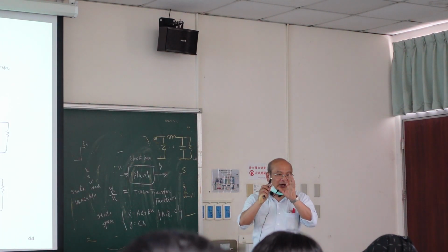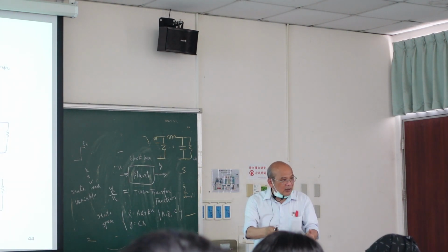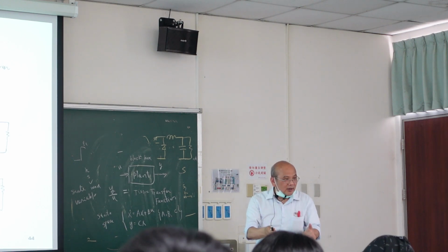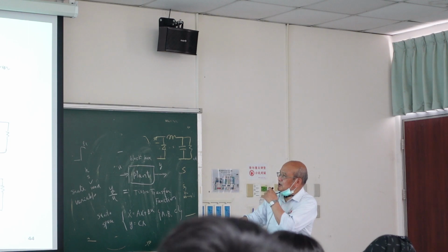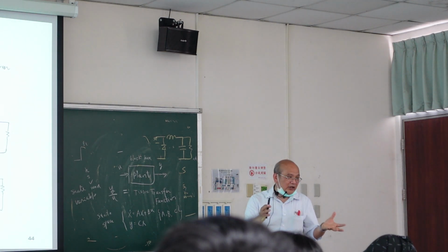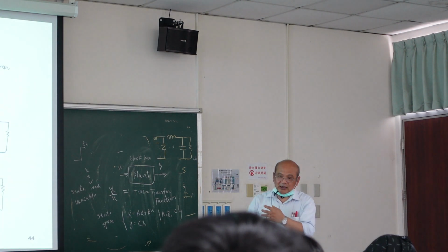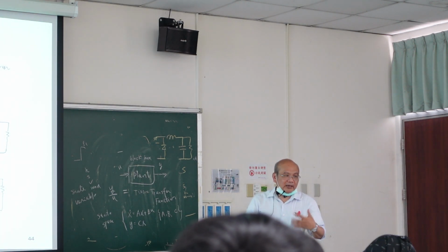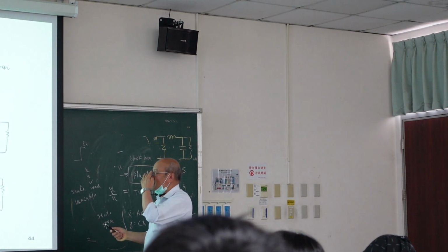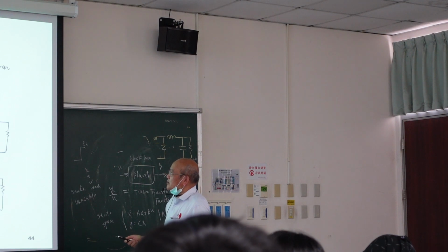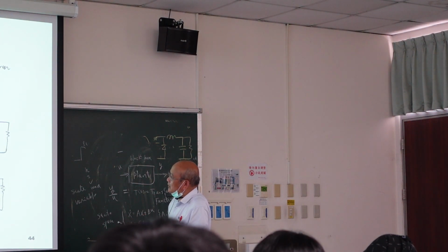You can say, what is my desired response? What is my real response? What is my bandwidth? And what is the relationship between the duty cycle and the output voltage? What is the relationship between duty cycle and the output ripple? So we can develop a lot of math. So it is important. So the first one is AC equivalent circuit modeling.